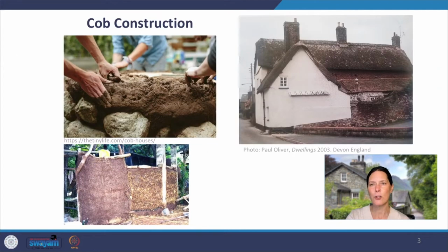We tend to think of adobe in hot, arid regions, and that's not wrong. But the United Kingdom has a history of earthen architecture. Cob is a loaf or conical shaped ball of earth that has been historically used in the UK and Ireland, both pretty wet climates. It's a relatively straightforward technology that doesn't need any construction forms. It's layered up, allowing time between each course for it to dry.